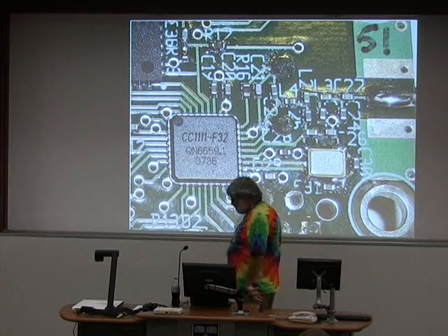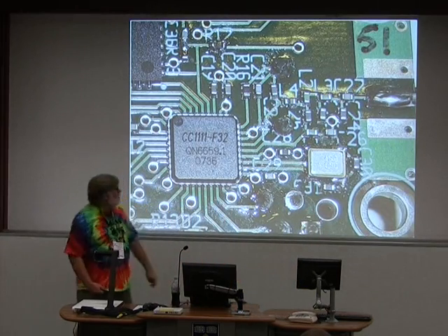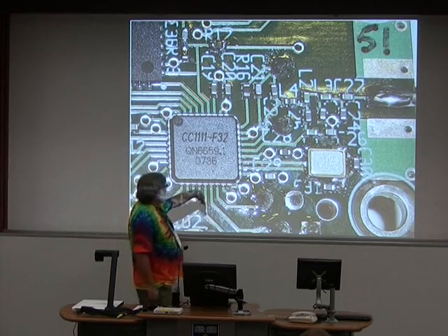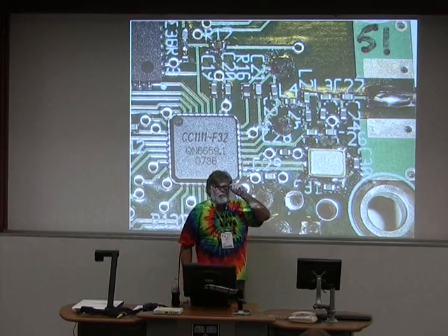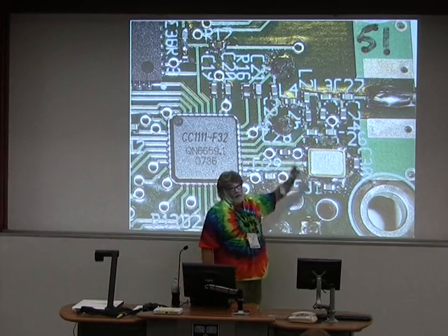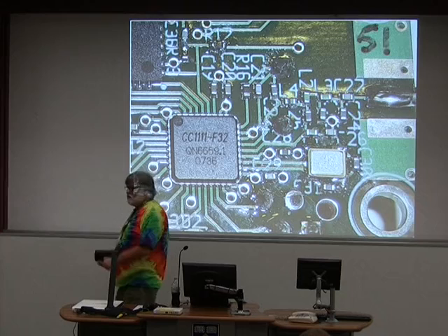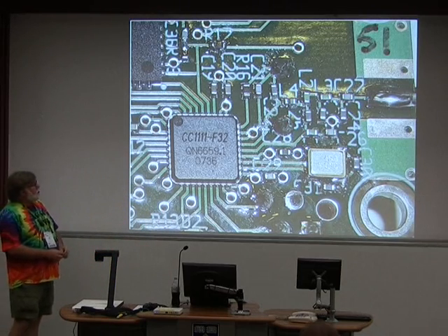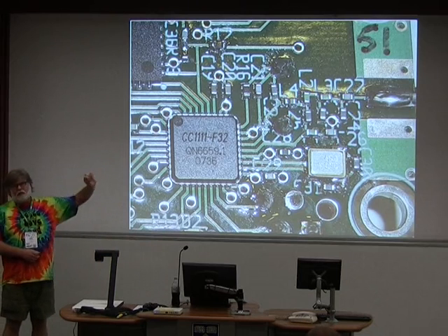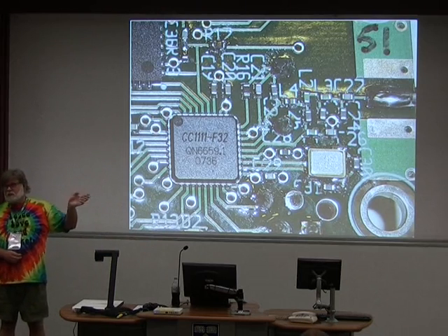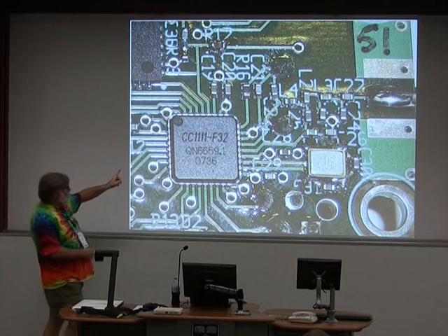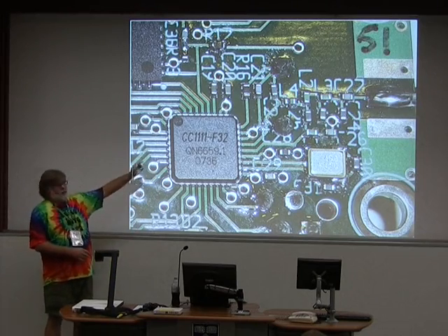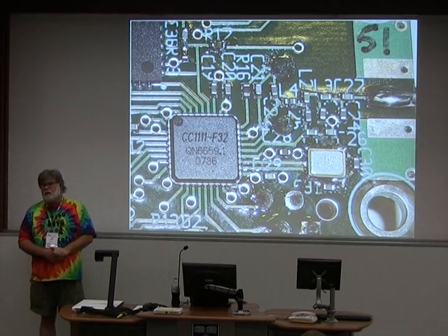This is a close-up of the CC1111 and the UHF end of the board. There are a couple things I thought I'd point out. First of all, the reference designs from TI ChipCon all talked about using 0402 sized surface mount passives for implementing filters. And that's because if you're doing this on either a thin substrate board or a 4-layer board, which is the most likely circumstance, to hit a 50 ohmish trace, you don't want to be a whole lot bigger than the 0402 passives.